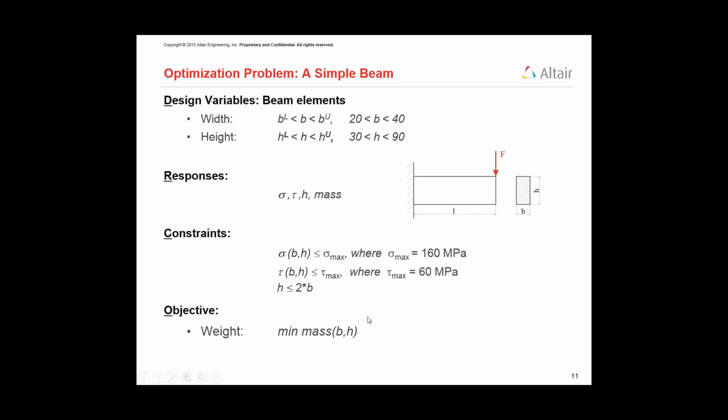We're going to say these are the limits that we want. And constraining is very important. I could say, you know what, I want to take this part and I want to minimize the mass and guarantee that I'm minimizing the stress, or the stress isn't going to go over a certain value. Well, guess what the optimum height and base would be to minimize the mass and guarantee that your stress doesn't go over a certain value?